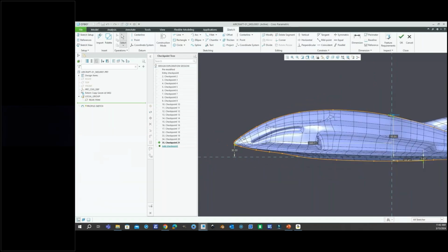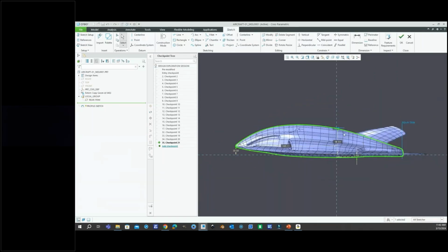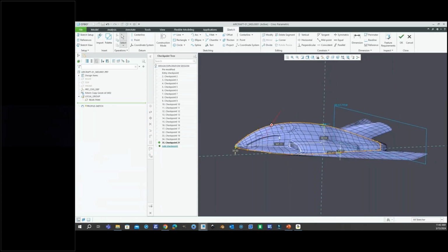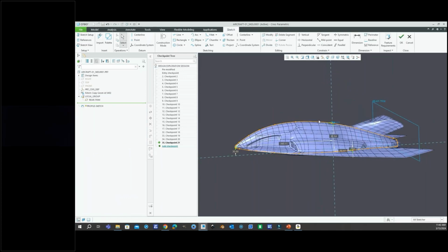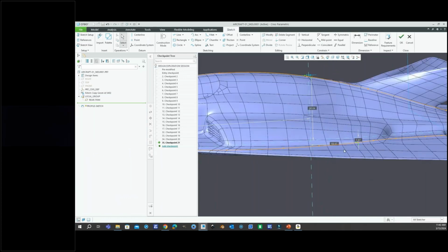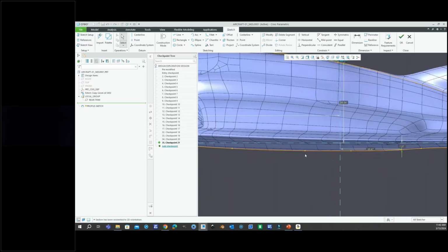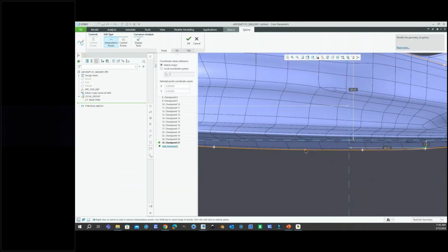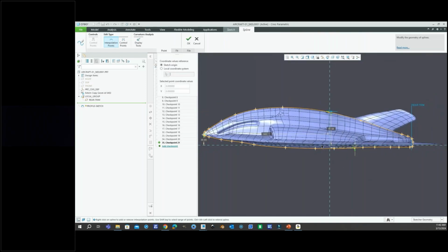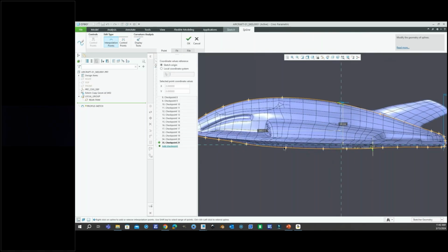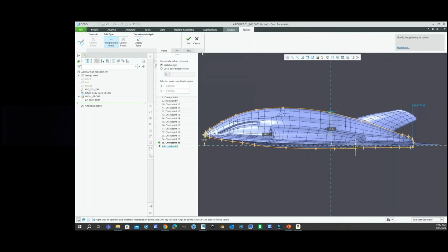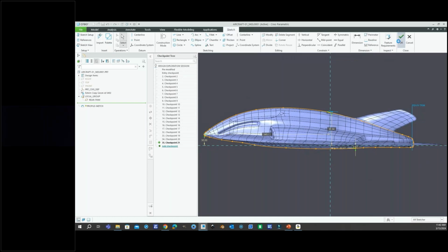Okay, so this is one spline. I wanted to make sure that I had one continuous spline, just so that my curves and surface would be clean when creating them. And I can always go back here and modify this. For example, if I want to bump up the surfaces, I can go in here, grab that point, drag it up, down, left or right. So after I actually create the surfaces with an ISDX, I can always come back here and adjust those too with these points. That's pretty powerful.